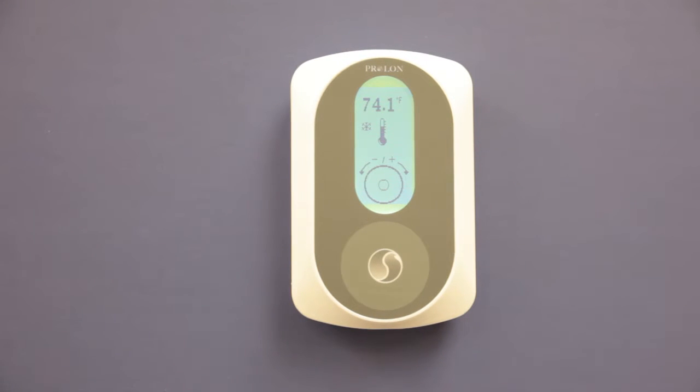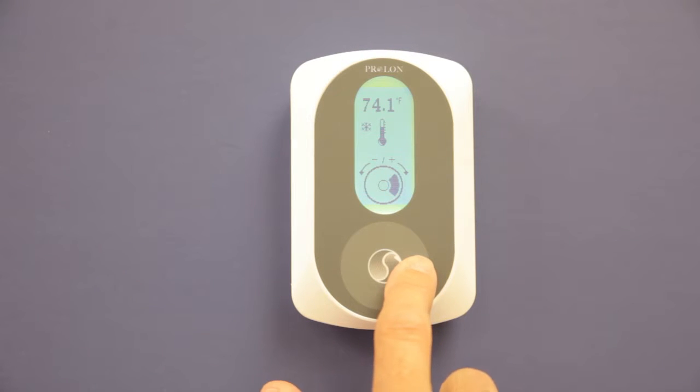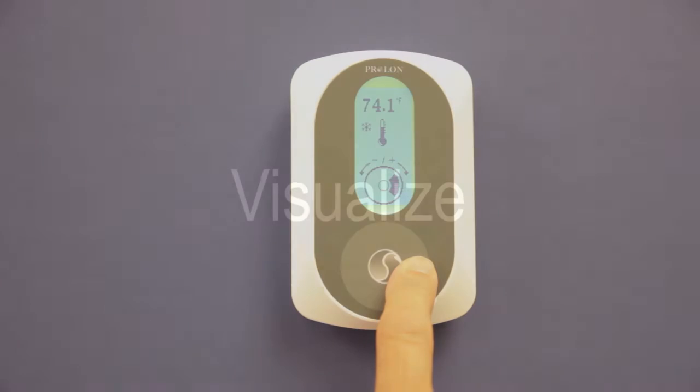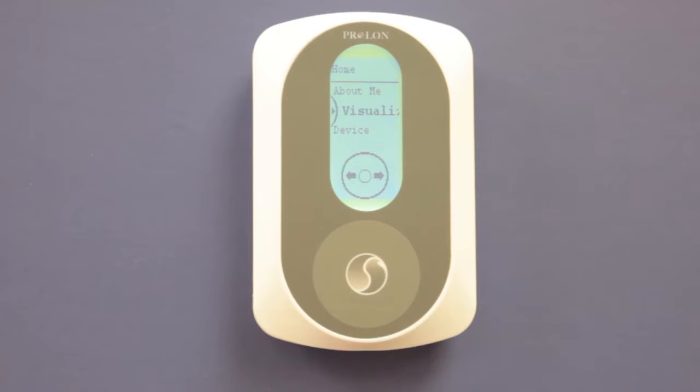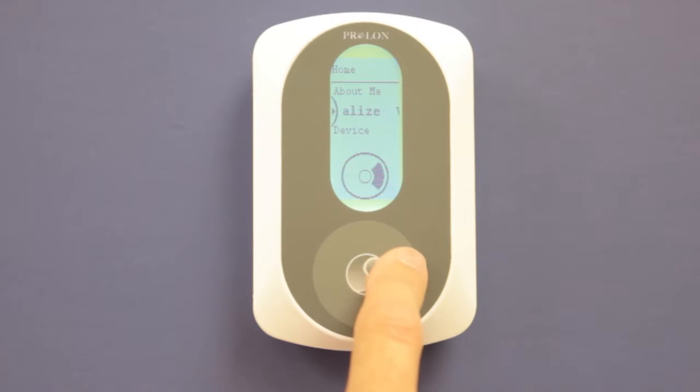To access the home menu, the T1000 must first be displaying the ambient room temperature. From there, press and hold the right side of the touchpad for 5 seconds. 4 submenus become available: Options, About Me, Visualize, and Device.